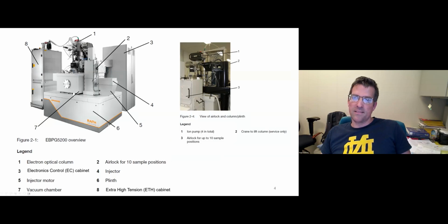Now, if you haven't seen an e-beam lithography system, this is how it looks. This is the electron column. Here is your load lock and the insertion rod. This is where all the different tables live, where you can insert different substrates. So as I said, small chips, small wafers, masks, and even up to a 200 millimeter wafer as well.